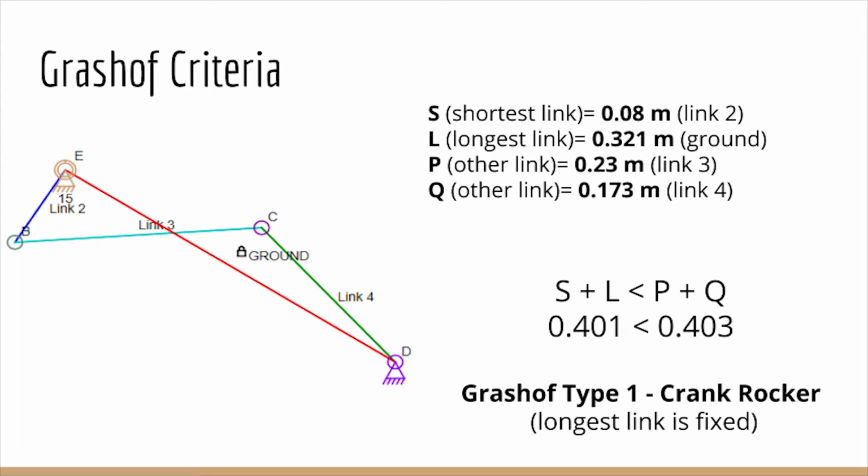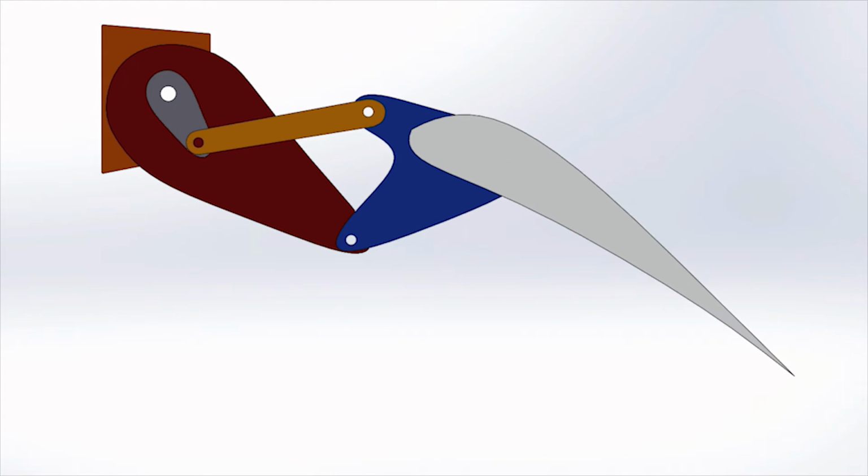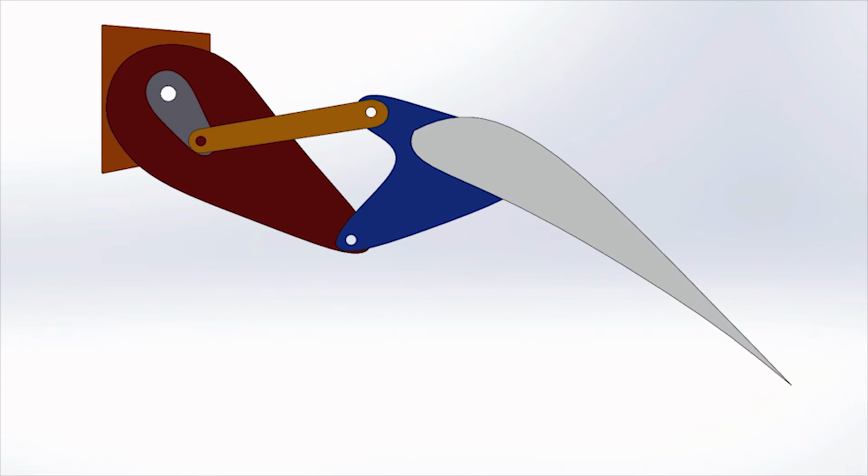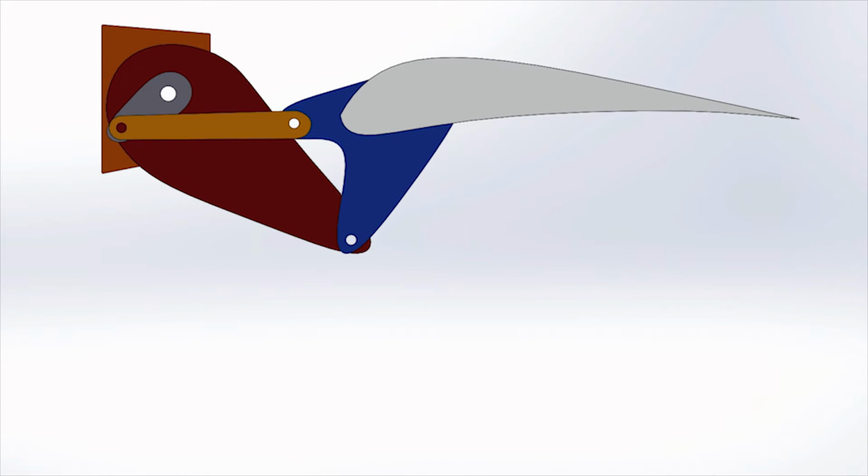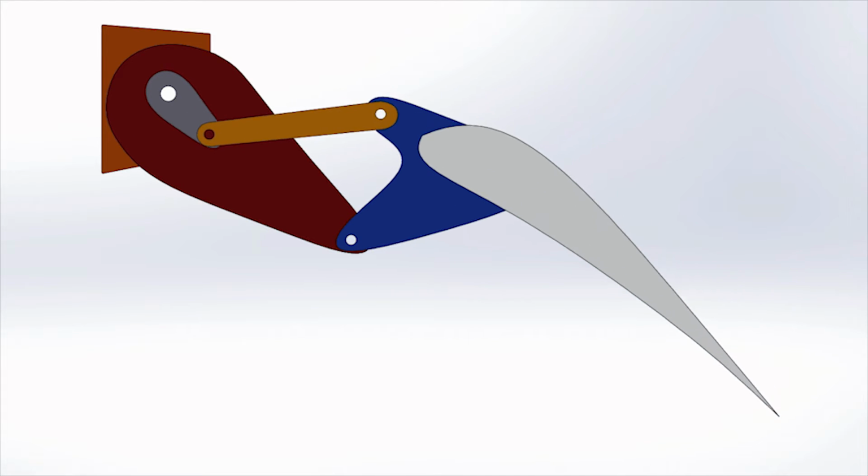The blue link 2 has the ability to crank 360 degrees, but for the purpose of our project, the crank can only function within a range of 124 degrees, allowing the aileron to decline 43 degrees as required. This is a quick animation showing the side view of the system. Note that the crank can only move in the designated 124-degree range.